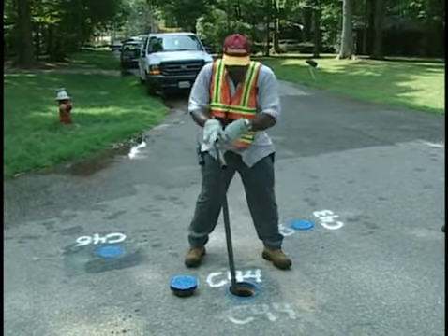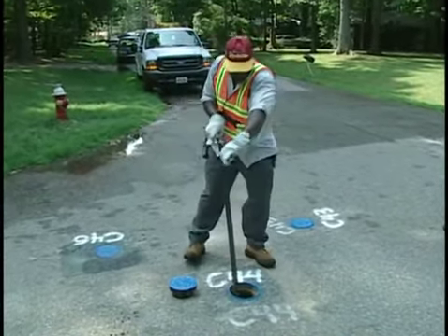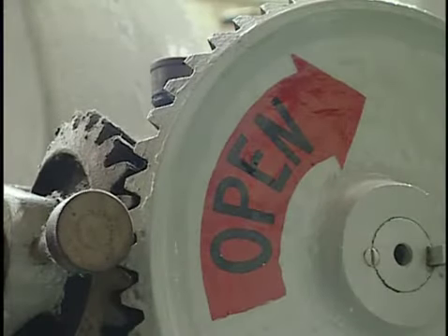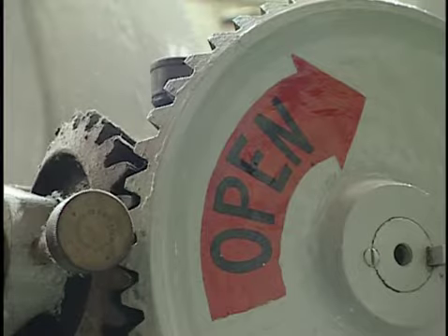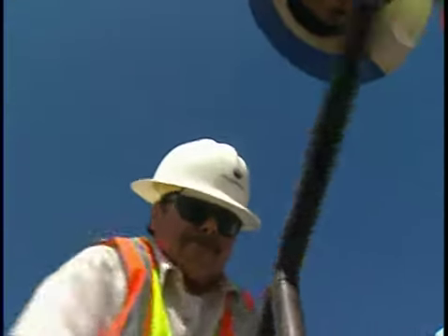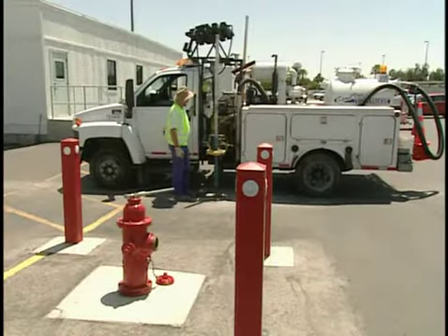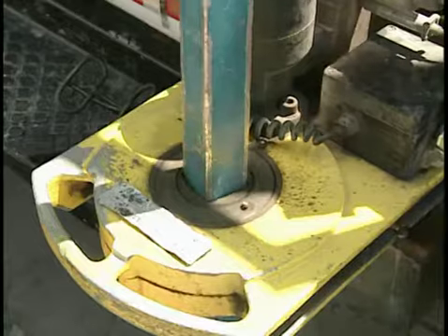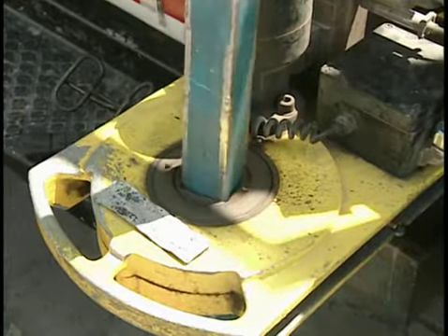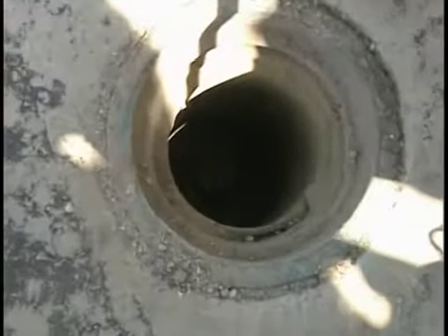Small and medium-sized gate valves are generally direct drive. Larger valves require a geared operator, and so several turns of the valve key are required to make one turn of the valve stem. Operators should count and record the number of turns for each valve in the distribution system. That way, when valves are exercised, it's possible to determine when they are fully open and fully closed. Distribution system valves have a 2-inch square operating nut that is operated with a valve key.